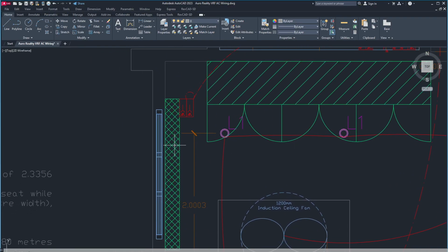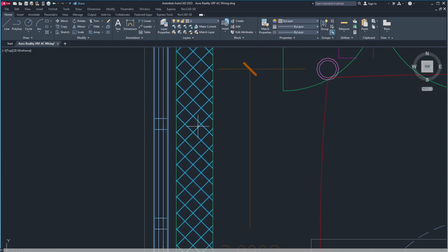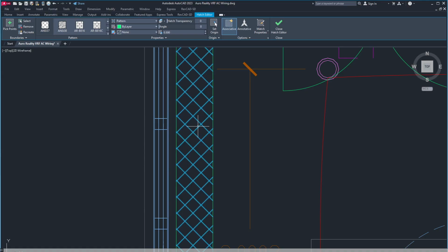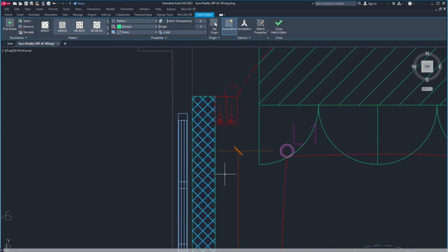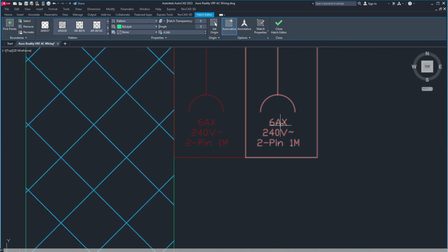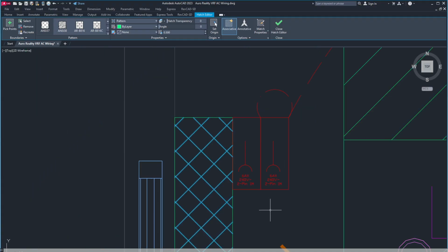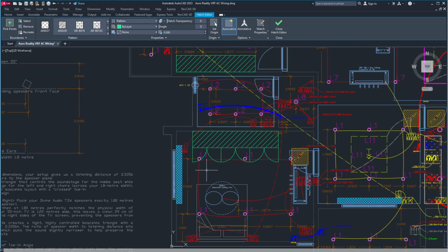And this is what? This is a curtain pelmet. Nowadays, people are opting for automation. So in the automation, they can control curtains also. There are two: one is sheer and one is blackout. So for both, we'll have two motors. If they operate one motor, then the sheer will open and close. If they operate the other motor, the blackout will operate and close. For that sake, I have given two 6 ampere 2-pin sockets here, because generally those curtain motors are imported from China. They come with a 2-pin plug. So we have provided for those also.